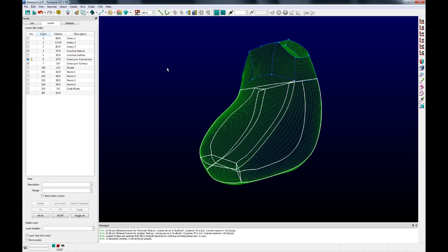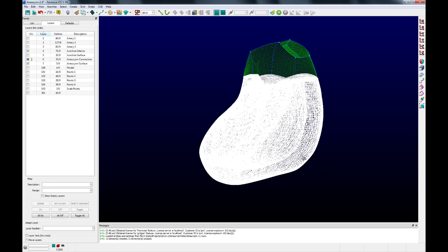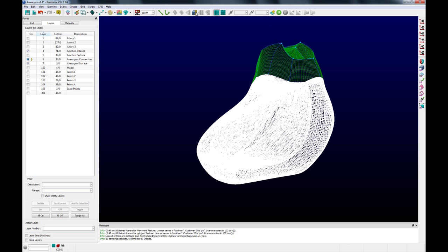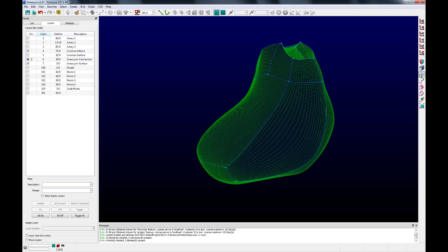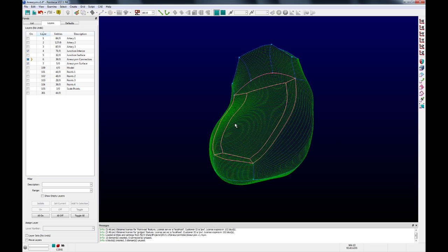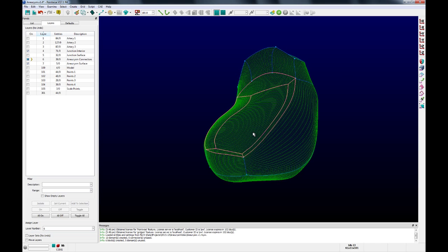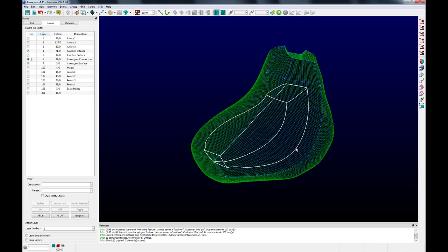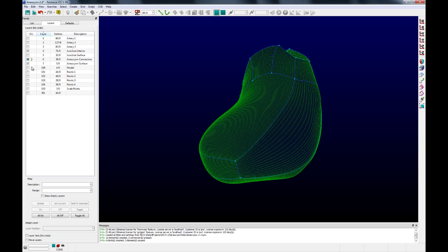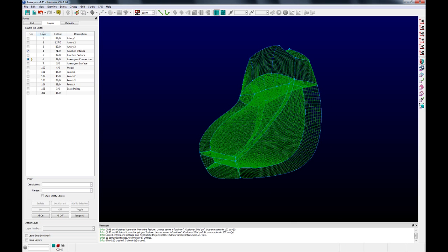We'll change our selection mask to include domains. We'll highlight all these domains and click on Assemble Blocks. By doing so, we create 6 blocks, which is what we expected. We have the tip block, and then the typical 5, the 4 OH, and then the central H core. So we're looking pretty good. I'm going to go ahead and turn the surface off just for visibility purposes.